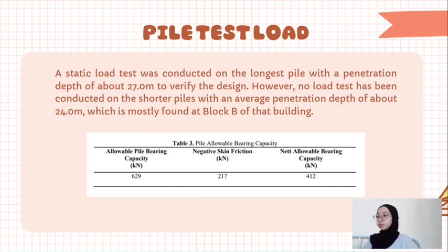Therefore, the main cause of the problem is possibly due to overloaded piles when subjected to the negative skin friction that develops over time because of the settling ground. This phenomenon has led to the occurrence of differential settlement of the pile foundation that causes cracks in the building.